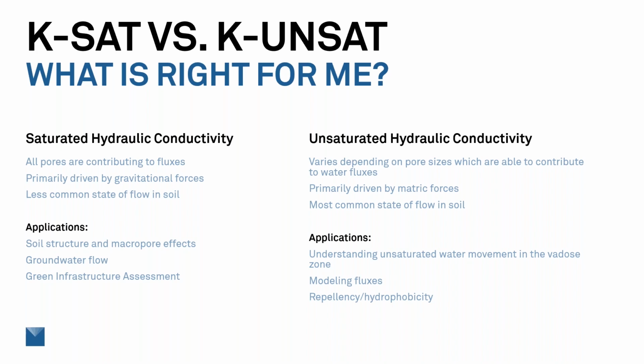It's also obviously in groundwater flow, you're going to be dealing with primarily saturated conditions there. So that's going to be more of an important measurement to make. And also when we're looking at green infrastructure assessment, so looking at a city's ability to, or areas in cities where we're trying to infiltrate more water and those types of things, we need to know what our max capabilities are. And that's where saturated hydraulic conductivity is going to be more critical when looking at low impact development types of things.